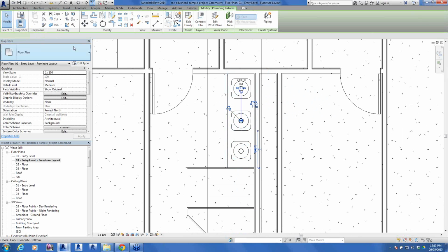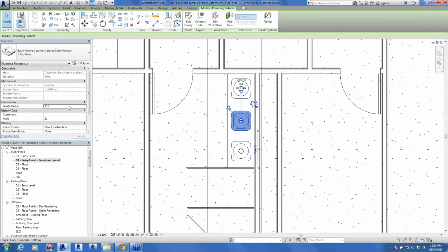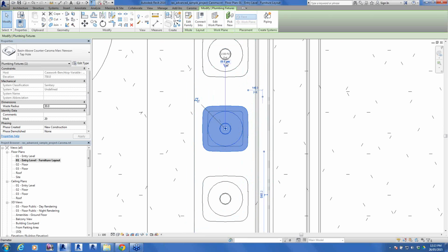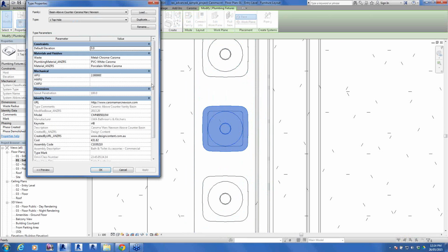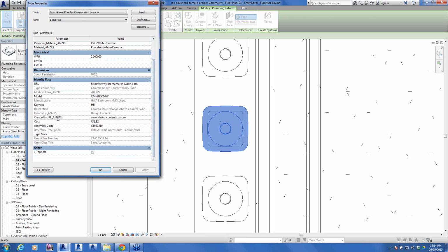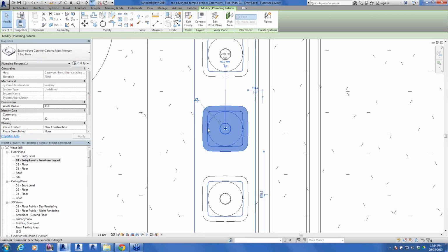Okay, we can see in the properties here we have a lot of useful information, waste radiuses. You can see we have connector information built in there, so we can connect up our MEP systems. So in this case, there's a sanitary system. We can look in the properties. We have links to fixture units, material controls, a lot of ANZRS shared parameters, so we can schedule that information, assembly codes, and Omniclass all defined. So as much of the metadata as possible has been set.